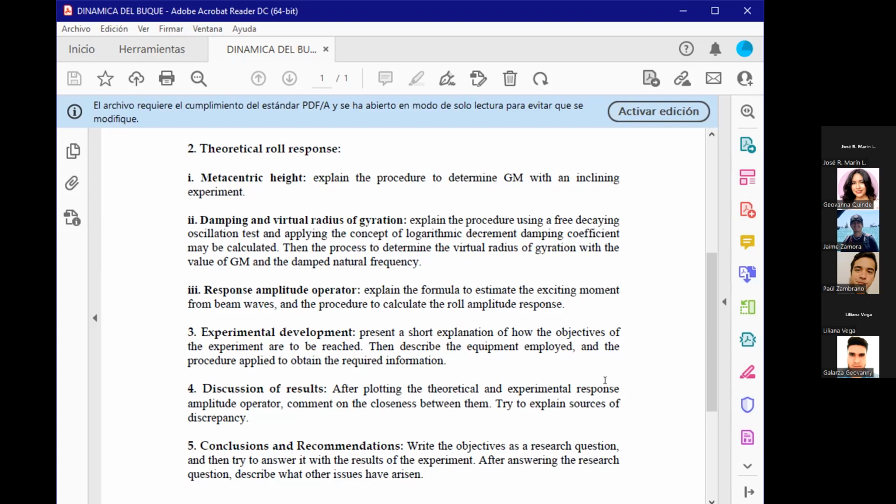You video record the incoming waves. From this video, you can determine the amplitudes, and also you measure the response. So from the response, you get degrees. From the video, you get centimeters in amplitude of the incoming waves. The quotient of those two is the experimentally determined RAO.